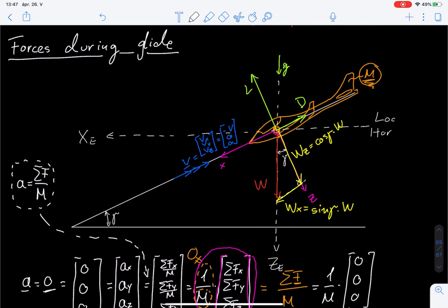Because we have just a very quick sketch: true airspeed, we have the drag, we have the drag for the light airplane, and if we add mass, the whole diagram is going to move up and to the right, and we will see that the drag is also going to increase. So, what's the final combination here, right? So how does mass, for example, influence the flight path angle? Okay, so to understand that a little bit and to understand the influencing factors a bit better, we need to do a little bit of trickery.